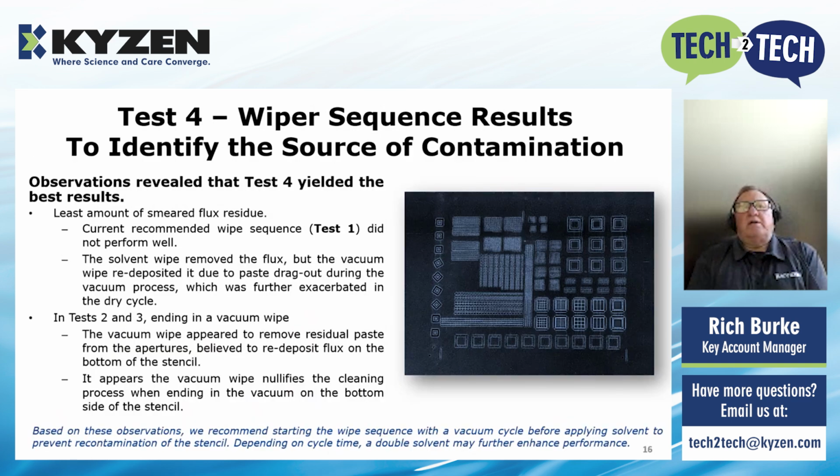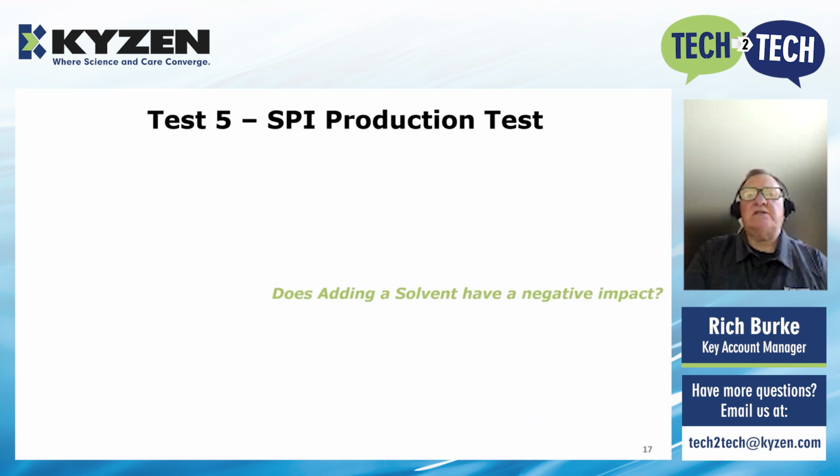Test 2 and 3 weren't bad, but again, it did show us that drawing the vacuum, drawing the solder paste out, did in fact have that negative impact, as I mentioned before, about smearing on the stencil. So we've now kind of walked through more solvent being better, saturation, increasing exposure time of the wet paper to the underside of the stencil is important, and the sequencing was important, right? So we've proven all that.